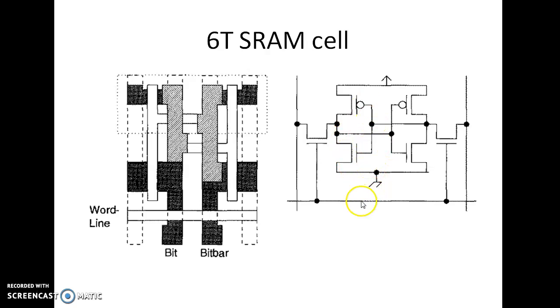These are some of the advantages, right? And you can design a 6T SRAM cell by changing the aspect ratios, that is the W by L values of the actual MOS transistors. So this is the concept of 4T and 6T.